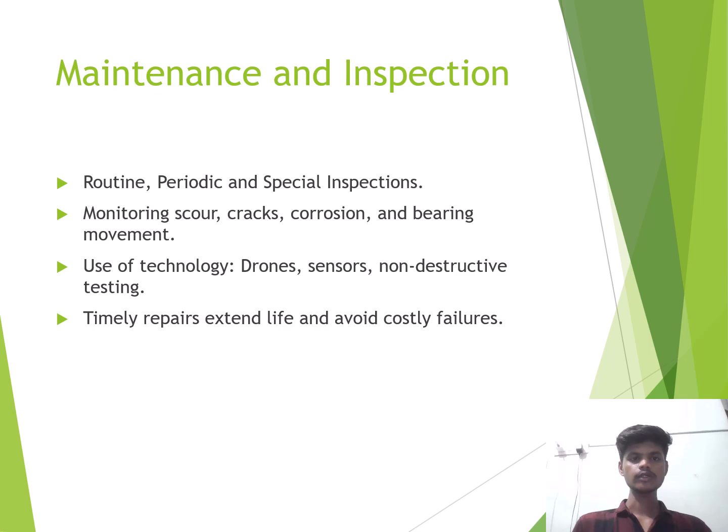Maintenance and inspection. Routine, periodic and special inspections, monitoring scour, cracks, corrosion and bearing movement. Use of technology: drones, sensors, non-destructive testing, and timely repair extend life and avoid costly failure. Maintenance and inspection means periodic inspections, monitoring of scour, etc.